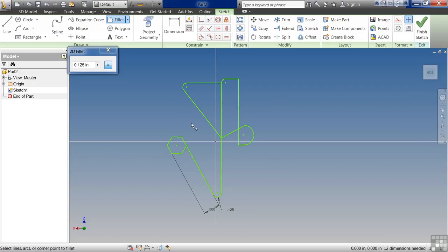While sometimes you must put the fillet into the sketch, it is a preferred method to add the fillet later to make it easier to edit in the modeling environment. By adding it to the sketch, I'm locking myself down to editing it in the sketch. That can make it kind of difficult to find which sketch it is in a real complex part. So only when necessary do I actually add a 2D fillet into a part.